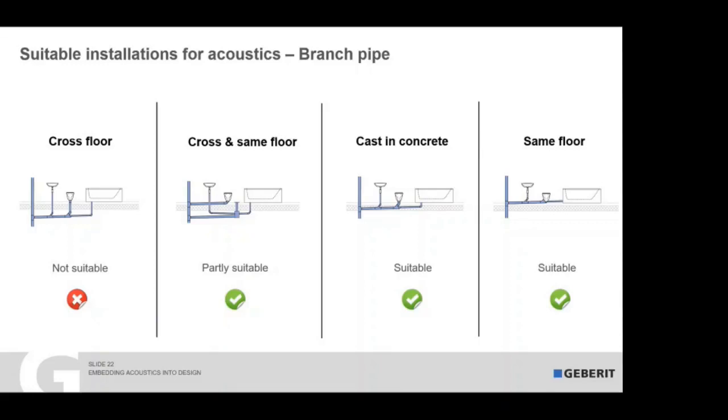But still, more important is the layout and the installation. So this is key, and that you consider the full system. So also use wall-hung toilets, decouple the whole installation, not only the pipe from the building, and then you will have good values.